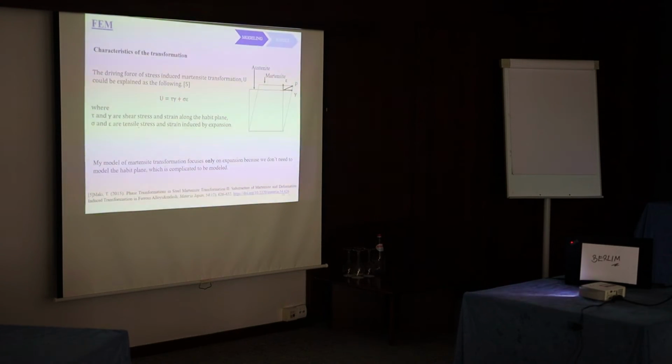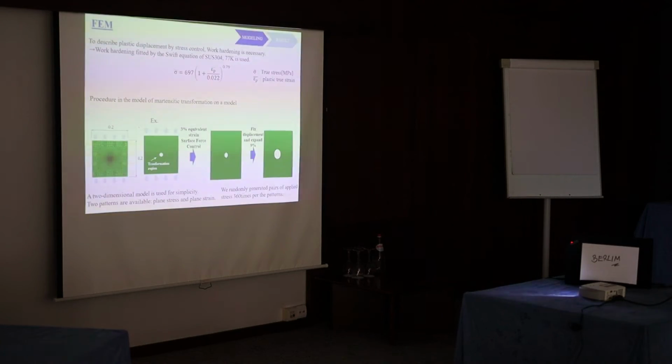It's kind of the shear stresses, shear energy, and more like expansive energies. My model of martensitic transformation focuses only on expansion because we don't need to model the habit planes. Habit planes are slightly complicated to be modeled accurately.